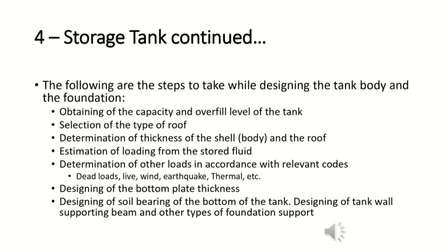In most cases for a storage tank, the outer edge closest to the wall of the tank and a little segment into the tank is supported by what you call a ring beam. This ring beam goes all around the bottom wall of the storage tank. Every other inner part of the storage tank is supported by the ground. So the stability of the ground and soil bearing of that area is designed for.